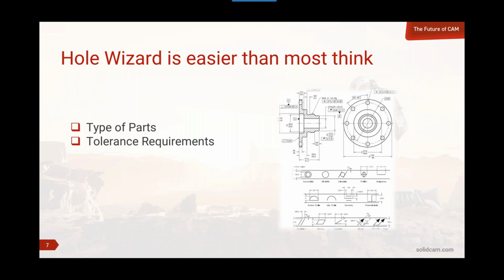Like I might, instead of just drilling the hole like we were talking about before, if it's got a locational tolerance, maybe I need to spot drill that to help keep the drill from walking. Maybe I need to undersize drill it so that I can come back in with a reamer and bring it up to a more precise size. Maybe I need to chamfer it at the end of it instead of doing it at the beginning of it. There's all kinds of different things to consider.